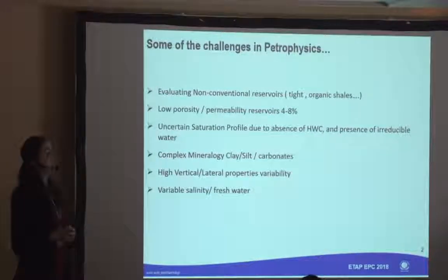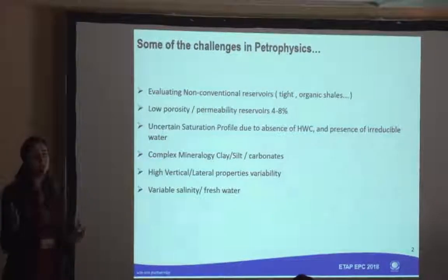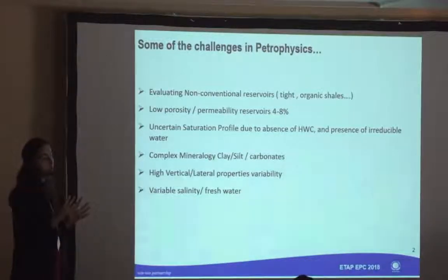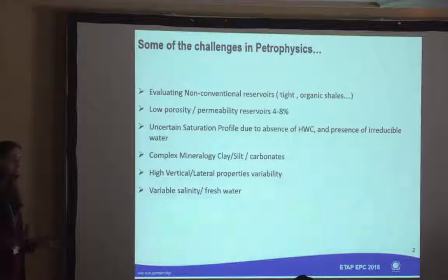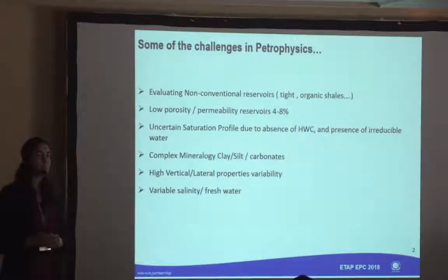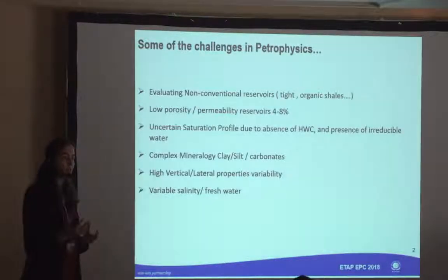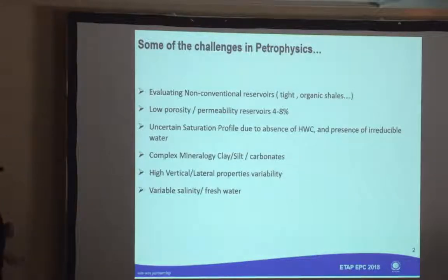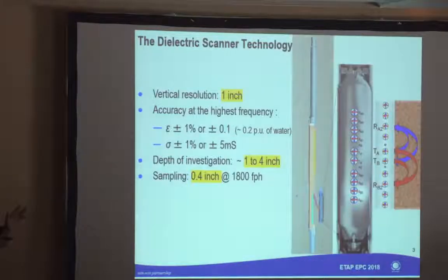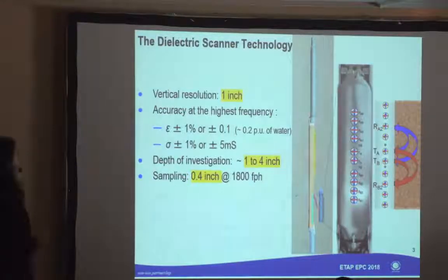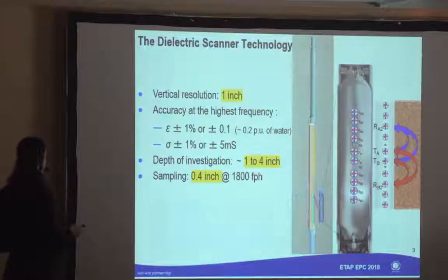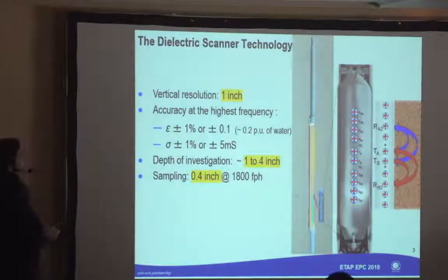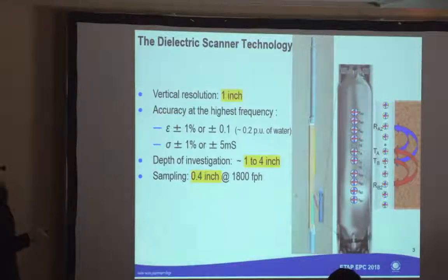And also we have the challenges linked to variable water salinity. For all of these challenges, traditional technologies and workflows are not sufficient to give us detailed formation evaluation. That's why we need some advanced technologies. One of these new technologies is the dielectric technology, which is based on the measurement of the permittivity and the conductivity of the formation with a very high vertical resolution, in the order of 1 inch.